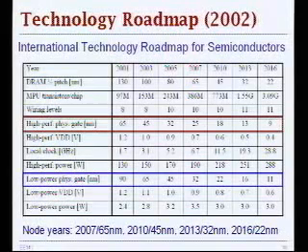And then during that 10% activity period, you have your underlying circuits that may switch internally about 10% themselves, because of the switching activity that gets reduced when you perform some logic functions. And what this leads to is that even in the worst case scenario, if you're really using your phone all the time, you maybe have the total activity of about 1% on average. And the rest, you are idling and you're consuming leakage, standby power. So that's why leakage is really, really important in this case, that you're trying to minimize the leakage.